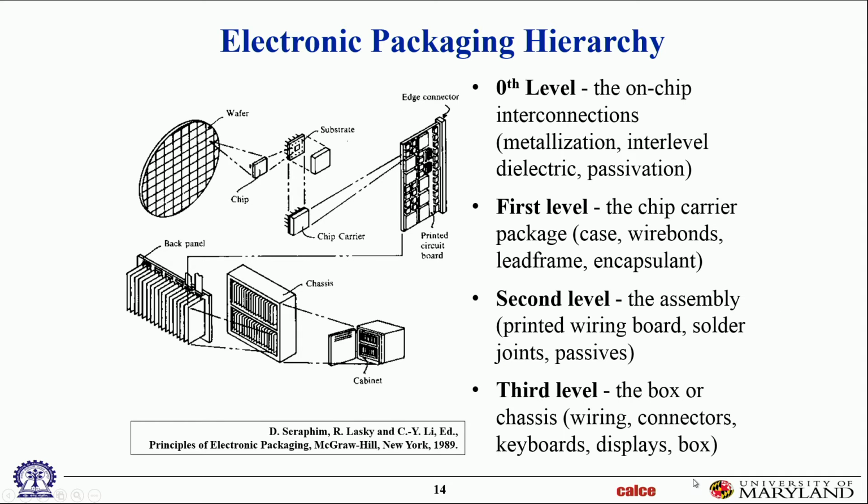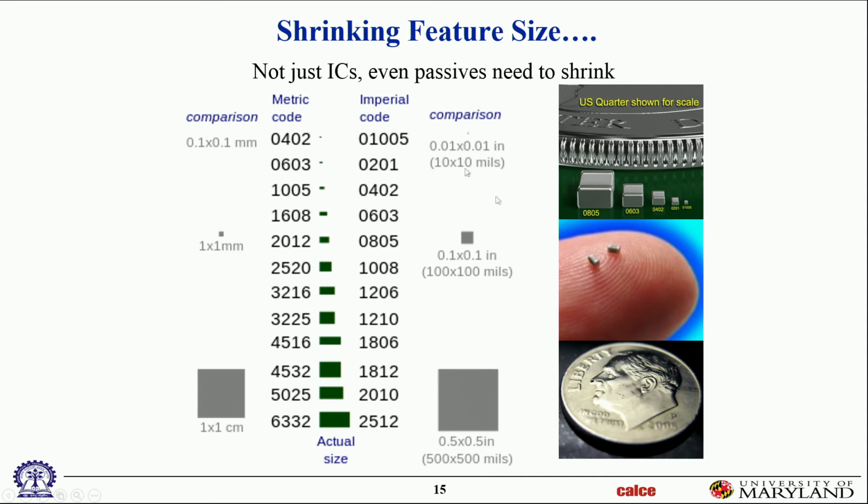Okay. And then this is just reminding you of the feature sizes. In this particular case, I'm just showing some ceramic capacitors, multi-layer capacitors. These are some of the larger capacitors in use. And you can see relative length scale. You can't really interpret that as actual size. Think of it as a relative size. So that's how tiny the 0402s are, in millimeters and in inches, compared to the 2512. So these are just acronyms, or rather catalog numbers for multi-layer ceramic chip capacitors.